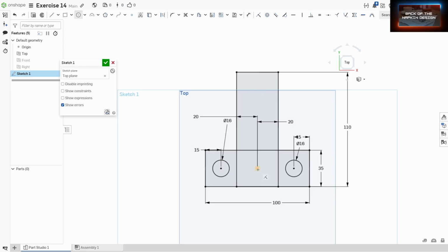Okay, and then let's go over here to circle. Circle. We can hover over this and then go straight up, and it gives us this dotted line. That means we're centered in there. So we're going to go with that right there. We're going to hit D for dimension, and we're going to make this 40. Enter. Okay, now D for dimension. We're going to position that circle.